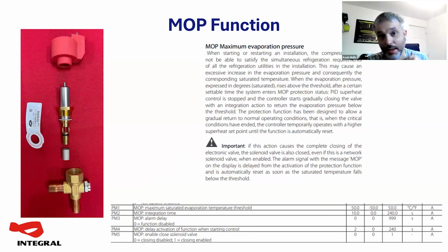Okay, so MOP, really important to mention. All of these controllers, and this has become much more relevant again on CO2, as people will know, on TEVs, TXVs, you could get a TXV that had a limited amount of charge in the sensing bulb, so that when you came off of something like a gas defrost, it didn't bang the valve to a massive, huge opening and flood back before it could react, or to control the pressure coming back to your plant.